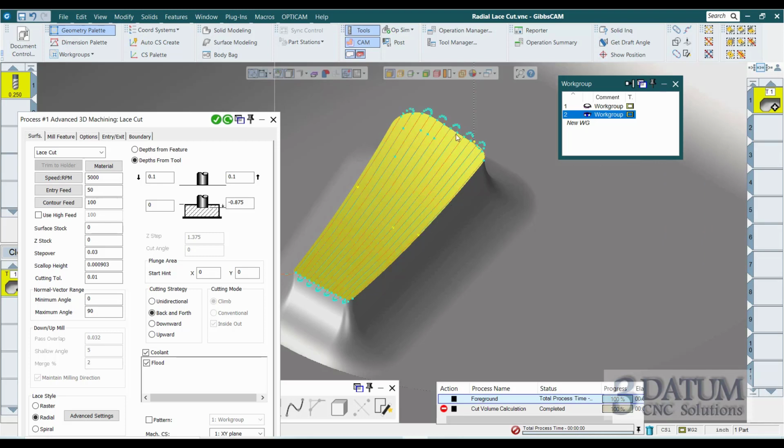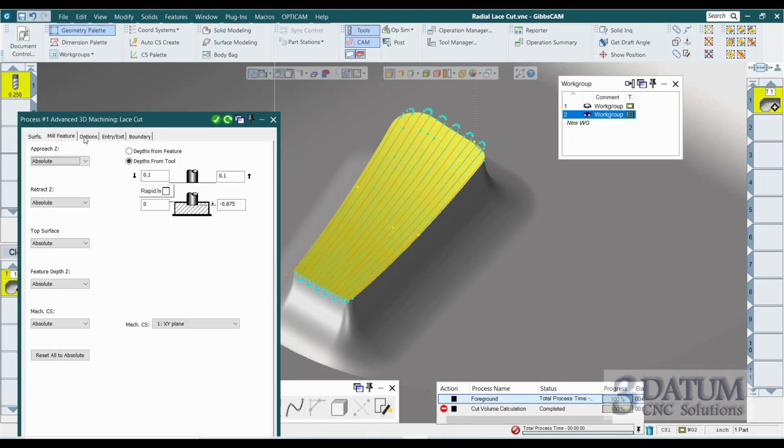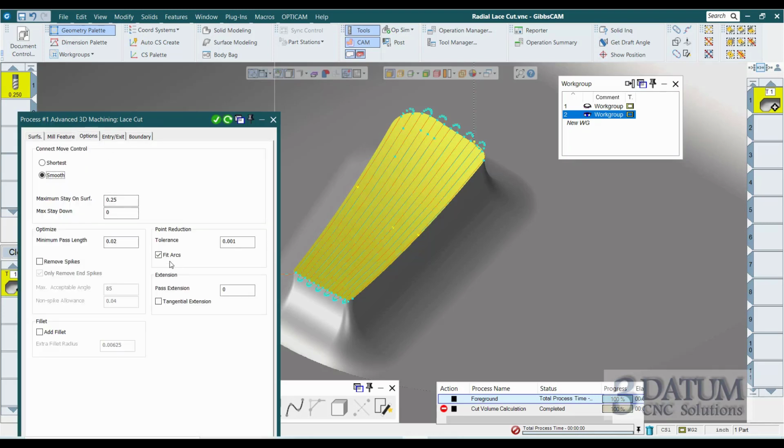All right, now this is fitting. I do have, I believe, yeah, fit arc. So we are getting some arc moves in here. So this actually is not going to be all that bad. But you see how few pieces of geometry along the stroke were created. I'm going to uncheck fit arcs, and the fit arc still had a tolerance of 1/1000ths.